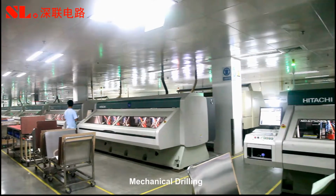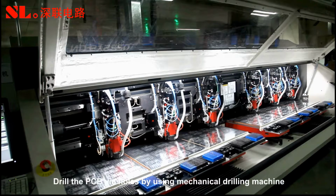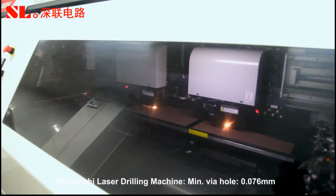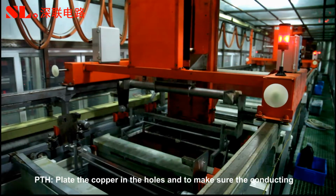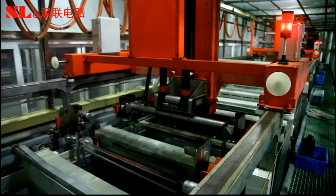Mechanical drilling. Drill the PCB via holes by using mechanical drilling machine. Mitsubishi laser drilling machine. Min via hole 0.076 millimeters. PTH. Plate the copper in holes and to make sure the conducting.